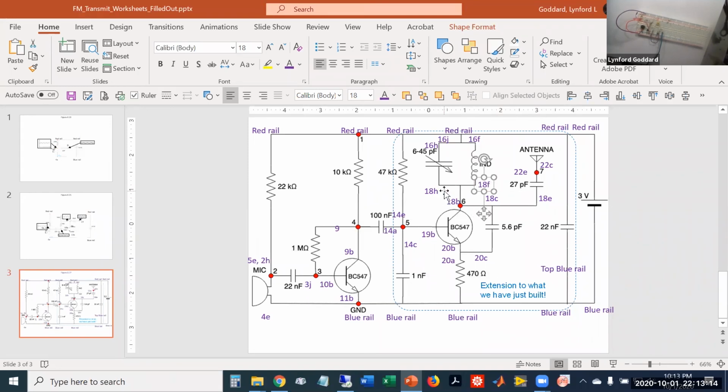So the challenge is it looks like we're done. The problem is the top half of the board is not connected to the bottom half. So I'm missing the jumper wire between 18 at the top and 18 at the bottom. So let's add another jumper wire. And it looks like with the available space, I can go between, let's say, 18J and 18D.